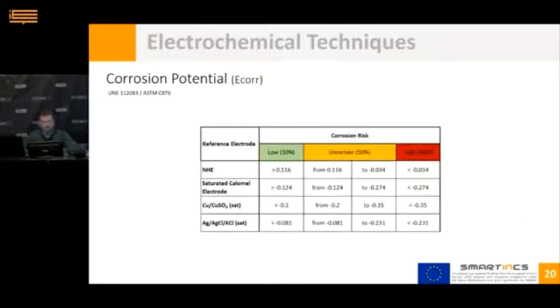The potential measurements will always be qualitative, since the value recorded is linked with the risk or probability that corrosion is occurring. The more negative its potential is, the higher the corrosion risk, establishing as a general rule 3 risk levels. Low, only 10% of corrosion probability, uncertain, 50%, and high corrosion probability, 90%.